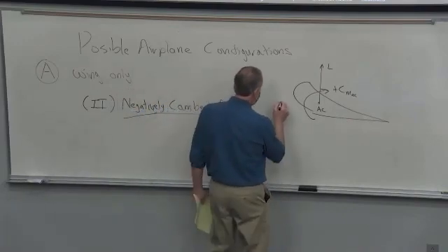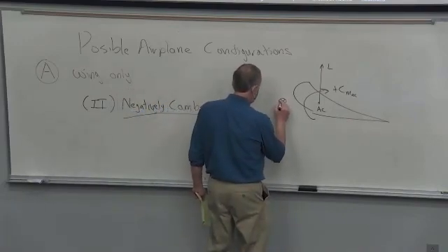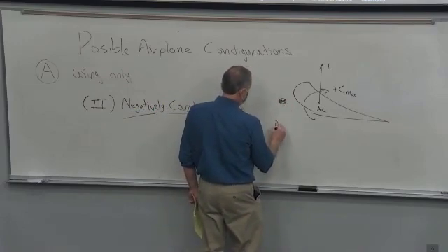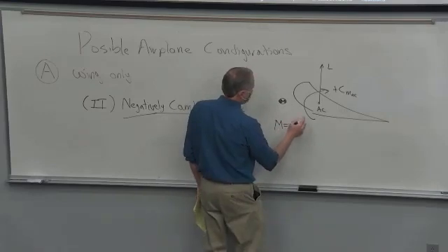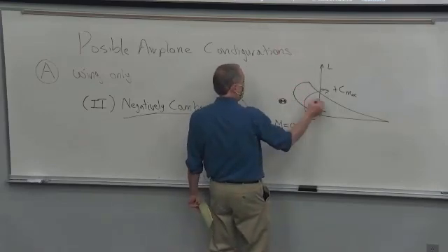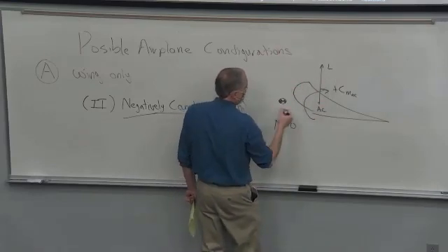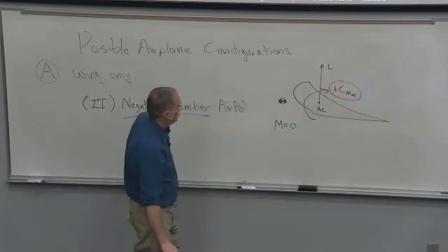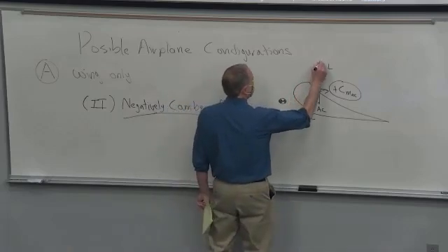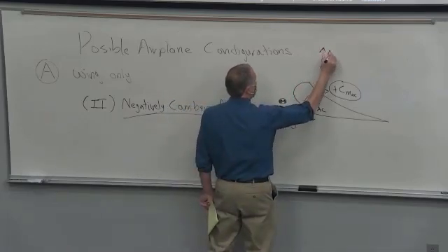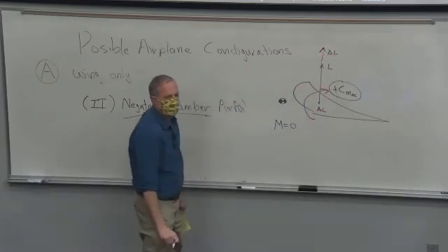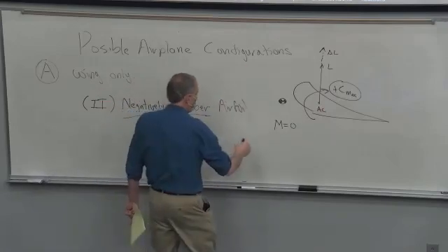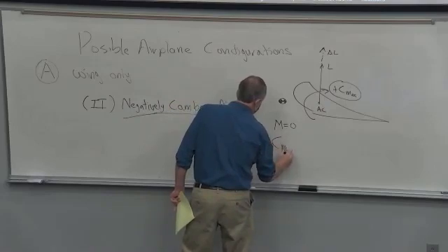And so if we put the CG here, we can get trim. We can get pitching moment 0 because the lift times this moment arm gives us a nose down, and the pure couple gives us a nose up. So we get that. How about stability? An increase in lift due to an increase in angle of attack, the thing pitches up. It's going to tend to nose down, and so we get good stability.